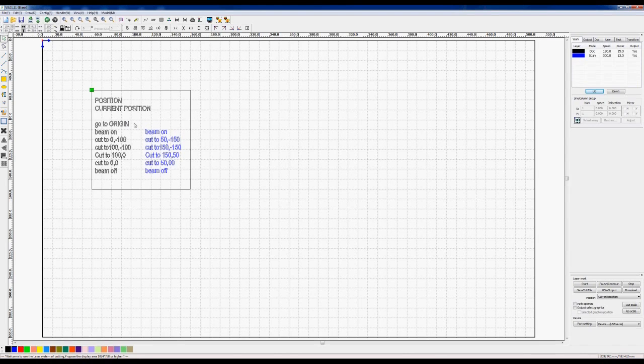I must adjust the program accordingly. So what it does, it rewrites this program temporarily. It doesn't mess around with the original program, but it just rewrites a temporary program which looks like this, which basically says, relative to the coordinates 0, 0, I need to move down to minus 150 in y, and I've got to be at 50 in x. So what it does, it converts these temporary coordinates here for the object into real world coordinates relative to 0, 0 by adding on the current position in memory for the origin.